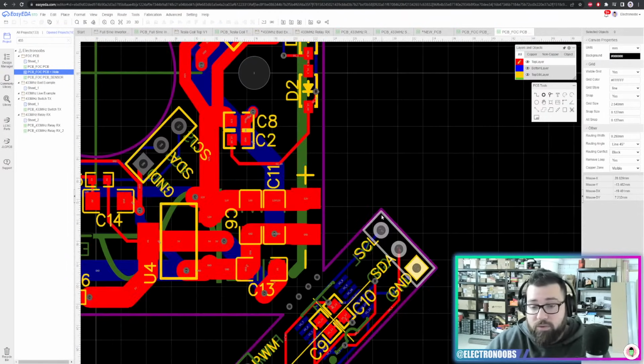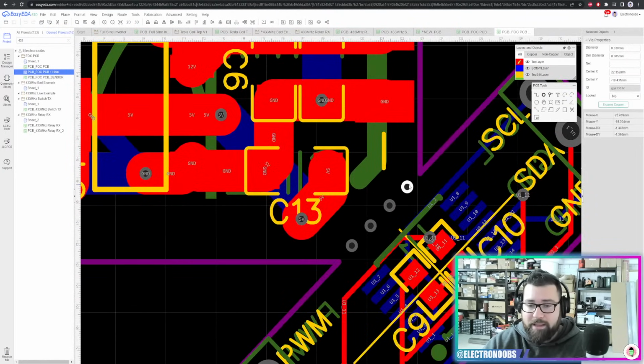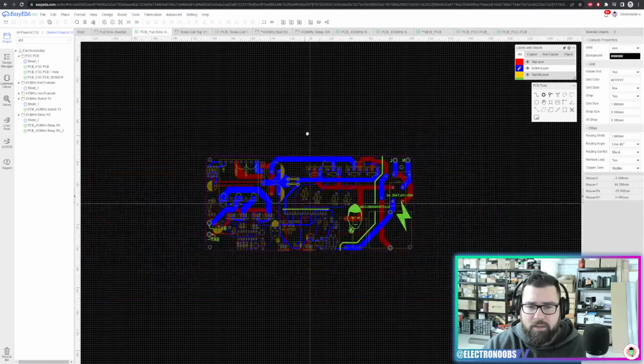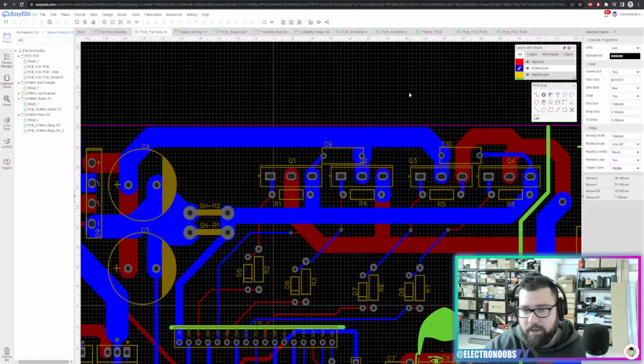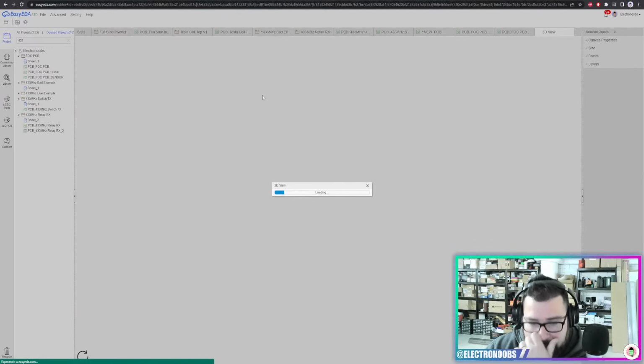That's another idea you could use: just set the outline of the PCB and add these vias here, so you could break it easily. Now I should maybe talk about this PCB, if you have any other question about the tracks. I've already shown you how to expose the copper, so it will withstand a lot more current.